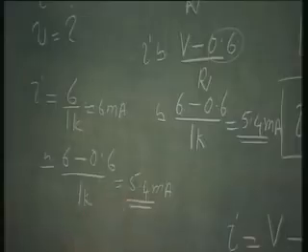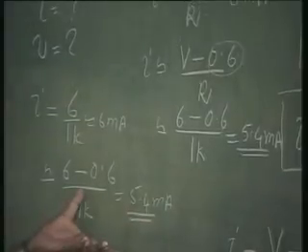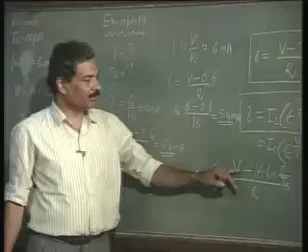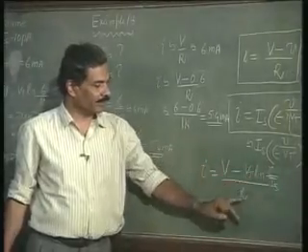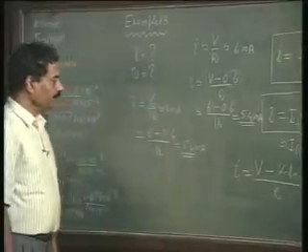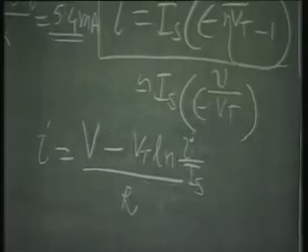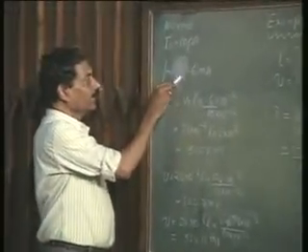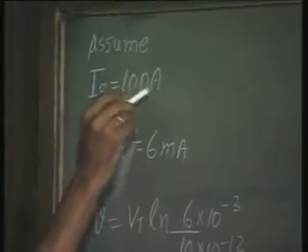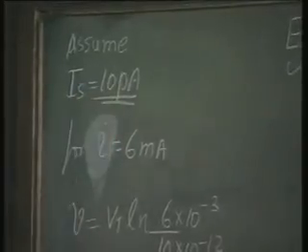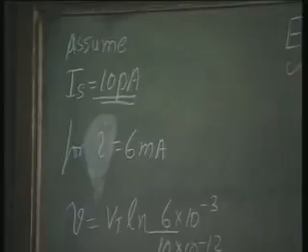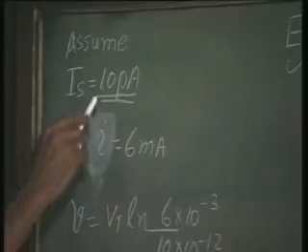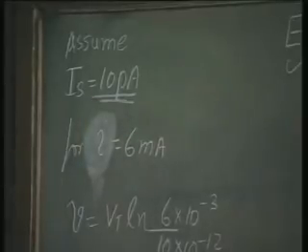Now, I want you to understand what is meant by solving this nonlinear equation. I is equal to V minus V, voltage across the diode, divided by R, R being 1 K. So, I had taken this as 0.6, but it is not 0.6. How much is it? Let us take I as 6 milliamperes, IS for the diode is 10 picoamperes. For such a diode with IS equal to 10 picoamperes, the characteristic may be known.